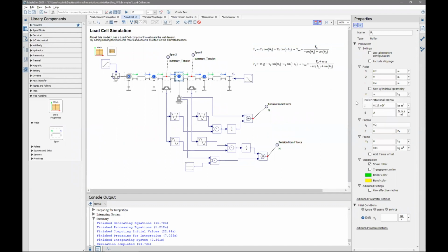And because they have inertia, they would create tension difference, and that amounts to error in the measurements. That extra force is not accounted for in this simple static derivation. But as soon as we hit the steady state, that error goes away.